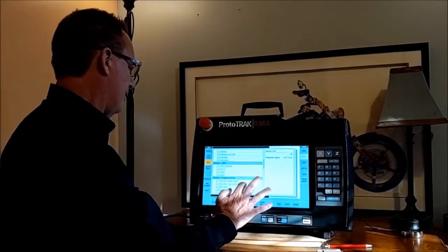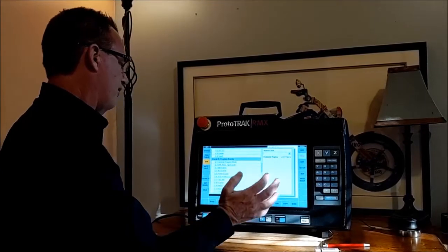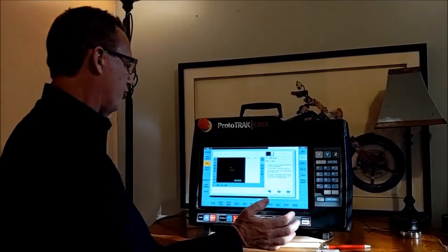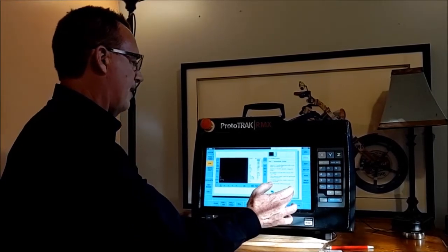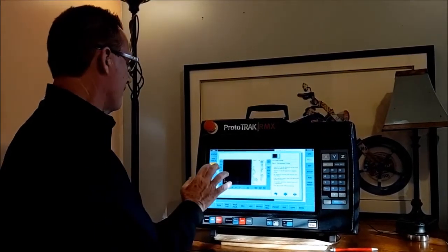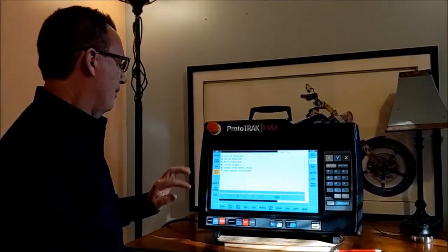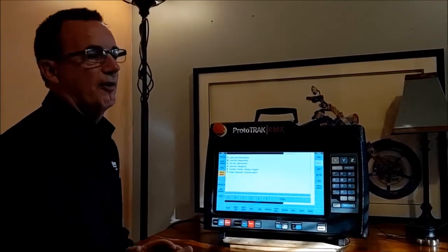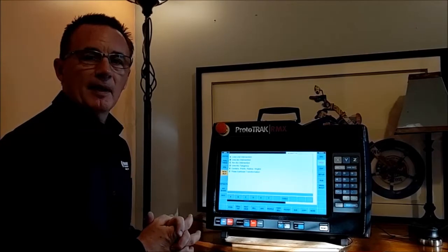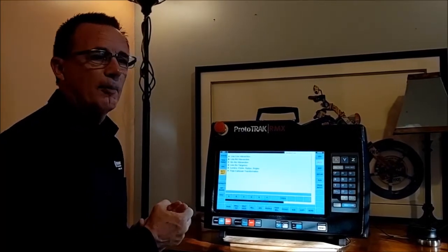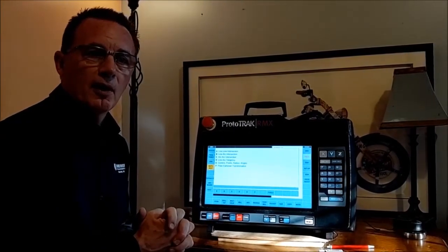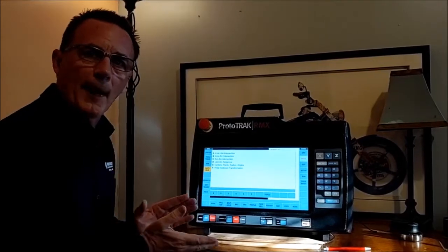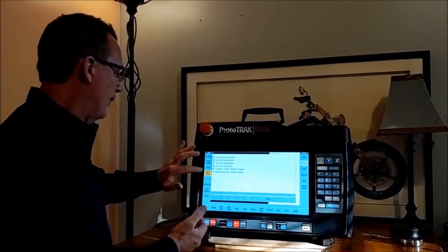What else do we have down here? Programming, profile events. It might show a picture in here. It's got a pocket, profile. So there's different things that we can look at. The math help, this is something that's been on the track machines for a long time. It's not new, but it's still needed, because sometimes when we program we need some help with maybe some simple math, or it could be trig, or it could be we need to find an intersecting point or an ending point. This is where we would go.